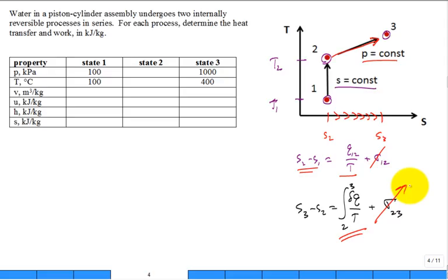Yeah, you can. They're two separate concepts. One is reversible, frictionless, think of that, and the other is just heat transfer. You said, but didn't you say if I have a heat transfer through a finite temperature difference that's irreversible? But in the limit, if you let the heat transfer occur with negligible temperature difference, so it's always matched, what you're bringing in heat from an external source into the system is always at the temperature of the system, so that there's no irreversibility due to just pushing it into the system,